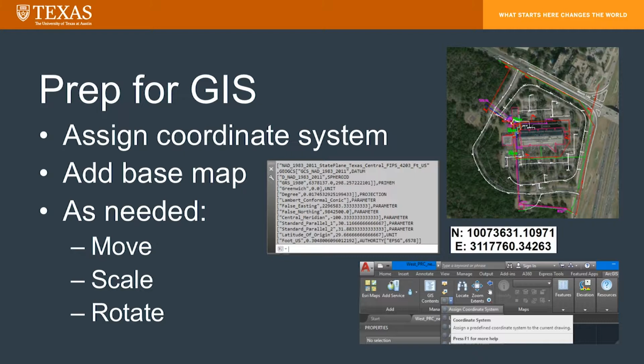So also real quick before we move on, I just wanted to note another instance related to the versions. Every time you go back to your AutoCAD DWG file and make a change to it, it'll automatically bring it back up to whatever your current version of AutoCAD is. So if you haven't already done the import into your GIS shapefile, you'll have to resave it down every time you go back into it.